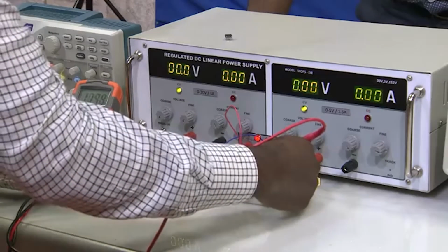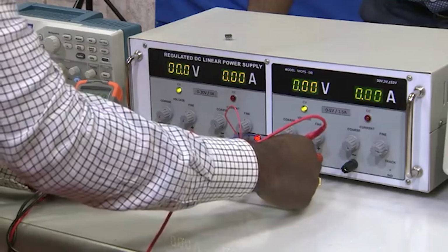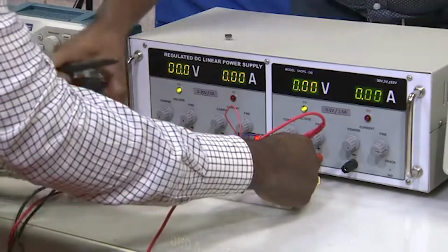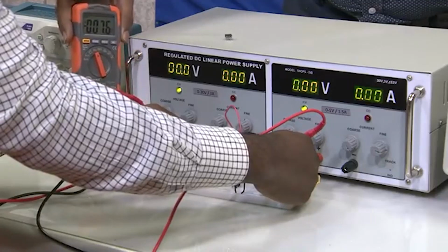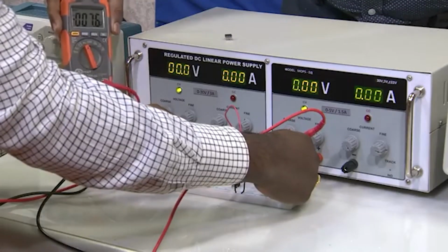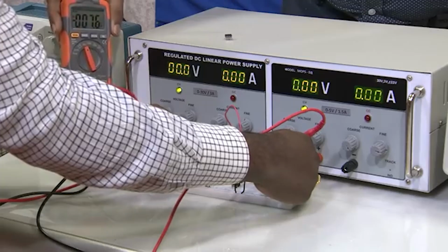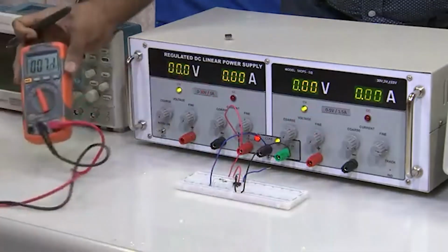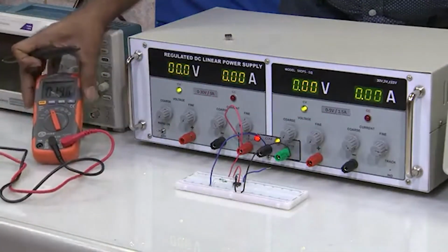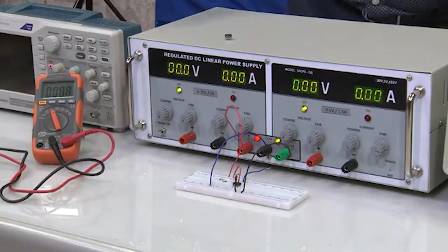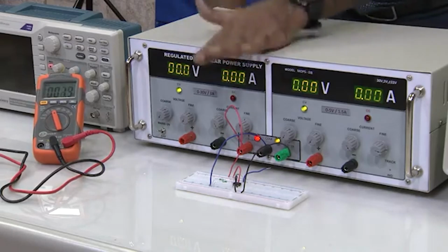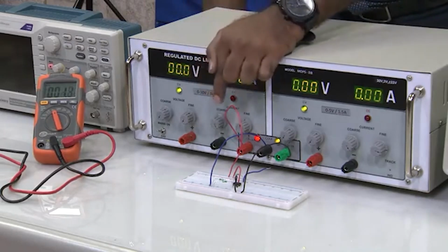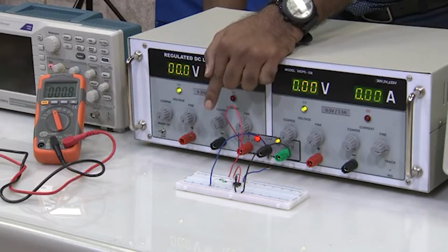So, he is connecting the positive to 6 and the other terminal to ground. What we see is some output voltage, 7.6 millivolts. Now, what should be the actual thing? The output voltage should be 0, right, but in a practical op amp, we are not able to get an output voltage of 0.